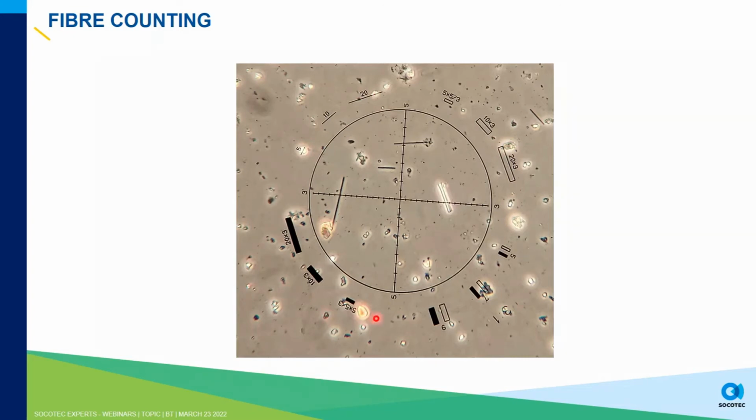The problem we need to be aware of when we undertake high volume sampling is that there's a risk of loading dust onto the filter that would obscure and cover the fibres. So there is a careful trade-off to be had when we're undertaking high volume sampling, so that we do not end up with dust-loaded samples. But the question is then, where can we undertake high volume sampling, and when should we undertake it? Why would we do it?